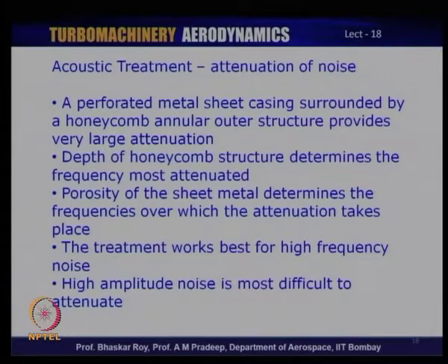So, the casing of the compressor or fan is made of such perforated metal sheet, and around the metal sheet you have honeycomb structures which also absorb a lot of noise. You remember, noise carries power or energy that has to be absorbed, and that results in a large amount of attenuation or absorption of noise.